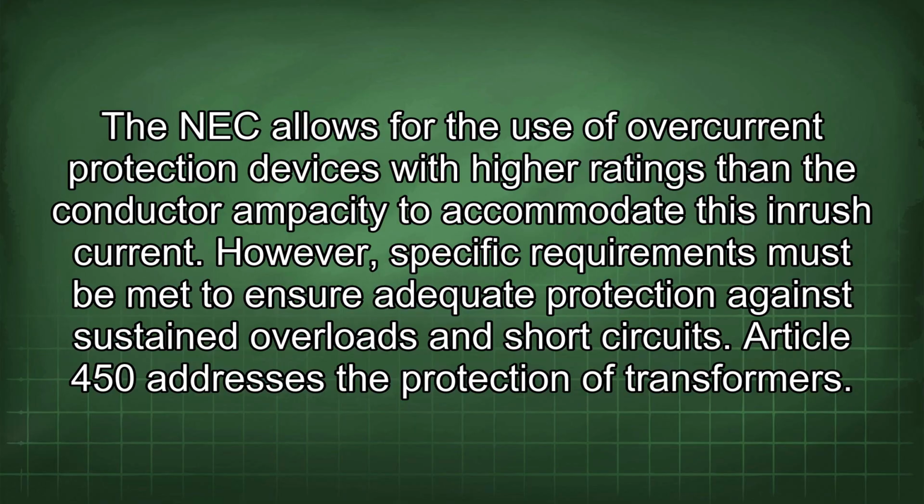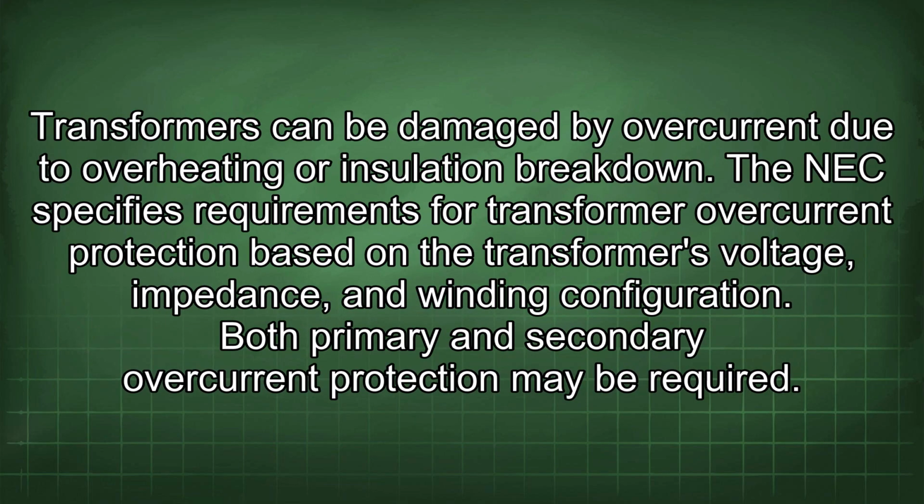Article 450 addresses the protection of transformers. Transformers can be damaged by overcurrent due to overheating or insulation breakdown. The NEC specifies requirements for transformer overcurrent protection based on the transformer's voltage, impedance, and winding configuration. Both primary and secondary overcurrent protection may be required.